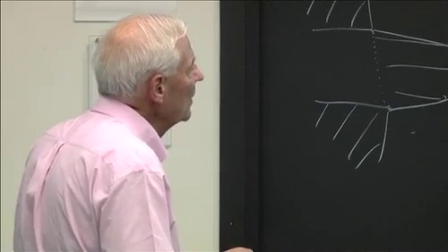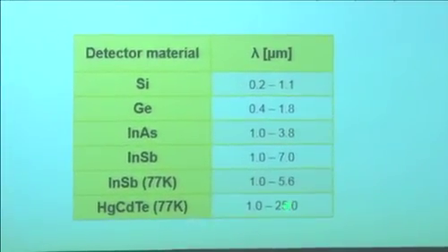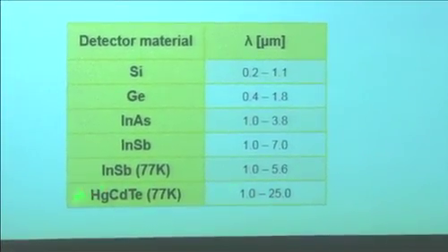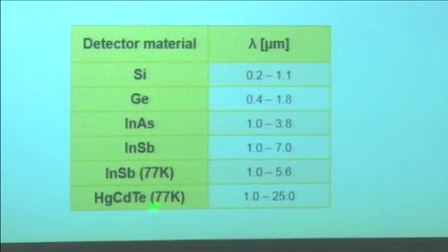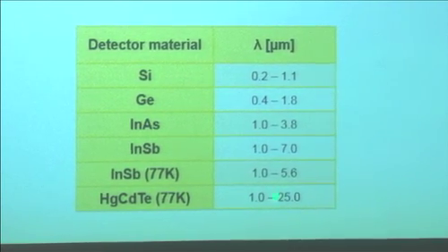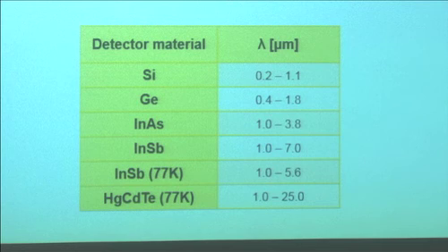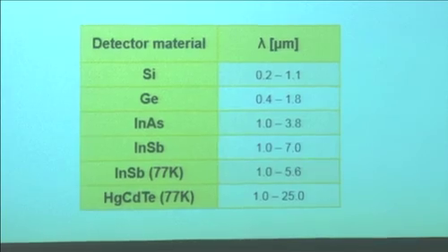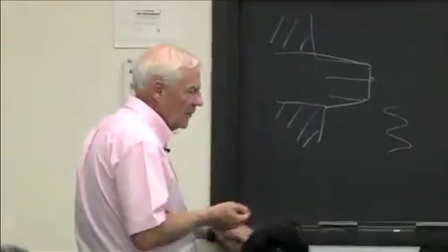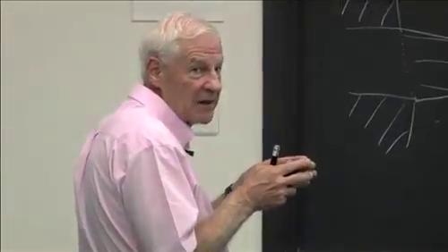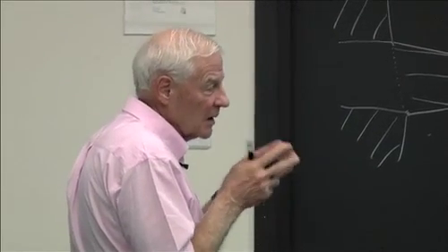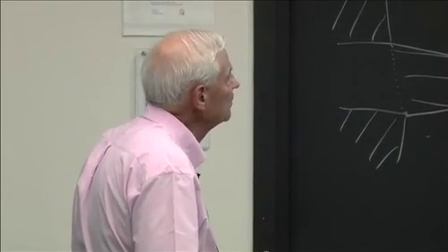But when you get out to the longer wavelengths, let's say you want to work at 10 microns, 20, you have to use some pretty exotic materials. The price starts going up. I think we pay around $6,000, or maybe 6,000 euros, I can't remember, for a detector out here at 10 microns. They're cooled with liquid. Everything's harder because those photons don't have a lot of energy, so you have to have a really nice detector. This is here in your notes. You can take a look.